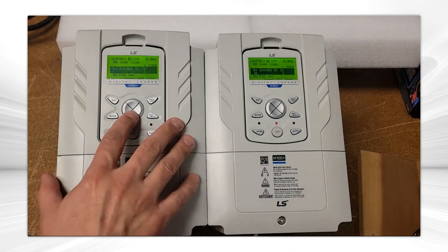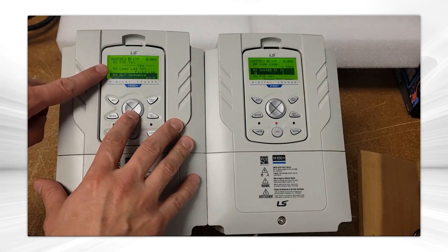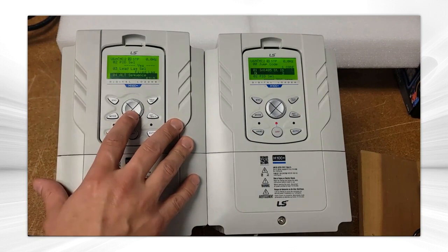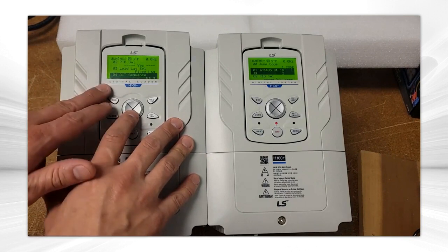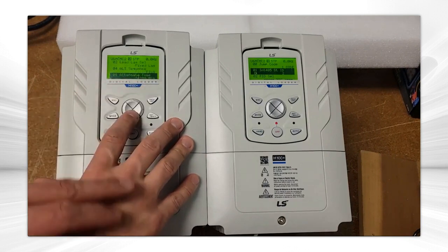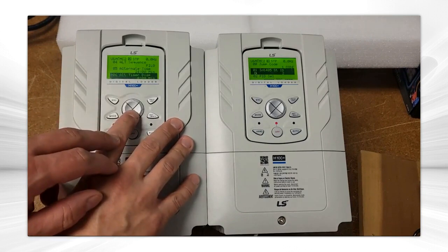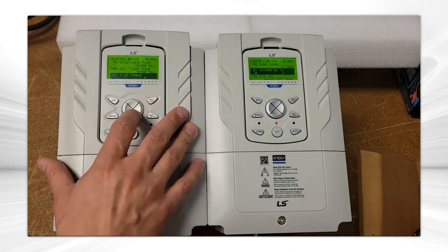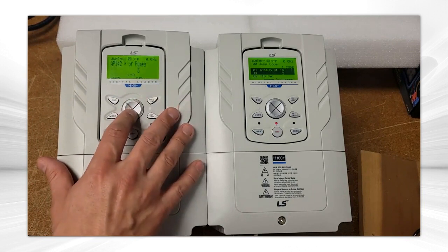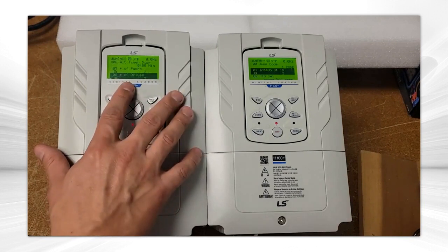You can see the other things the macro does: it enables PID, and it sets lead lag selection to be a fixed lag. So you can put a preset speed for the lag whenever it comes onto the system. Some of the things we're talking about as well are first in, last out. This is adjustable. We default to a 24-hour alternation time, and you can see that time count up as it is operating. I'm going to go ahead and adjust some of these parameters. So the number of pumps is going to be 2. And then it automatically takes down the number of drives.